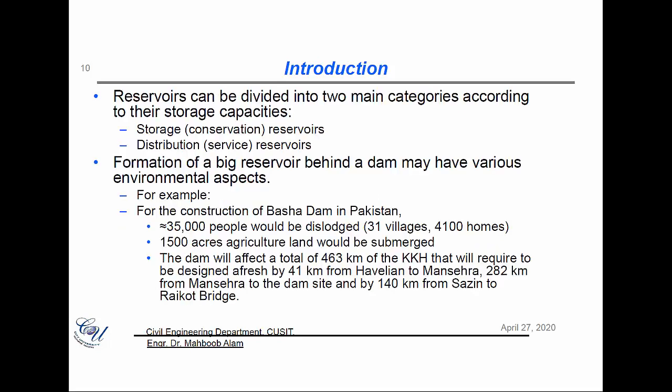We looked at the storage and distribution reservoirs, and we said that we can control the outflow from those reservoirs either through weirs or through gates, and related to both of them we looked at the hydrograph, how the hydrograph would be changed if we are installing gates or if we are controlling water with the weir.